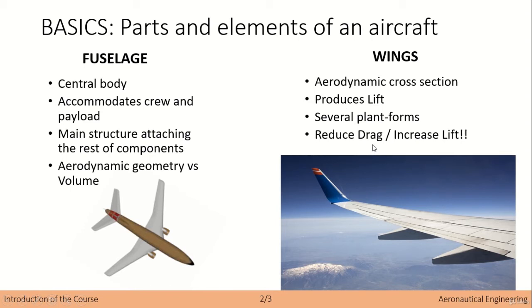As always, in terms of aircraft, the most important element is to increase lift in order to get upwards, but also to reduce as much as possible the drag, because a big drag would be a structural problem for the aircraft. And not only that, it means that we need more energy, more thrust, a bigger engine to get the aircraft moving. So in the end, a lot of effort is put into optimizing the airfoil and the geometry of the wing in order to optimize the ratio between lift and drag.